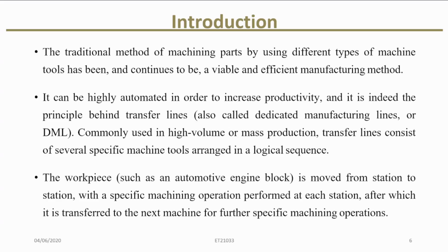and it is indeed a principle behind transfer lines, also called dedicated manufacturing lines or DML. Commonly used in high volume or mass production, a transfer line consists of several specific machine tools arranged in a logical sequence. The workpiece, such as an automotive engine block, is moved from station to station with a specific machining operation performed at each station, after which it is transferred to the next machine for further specific machining operation.